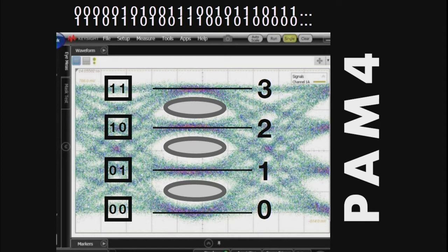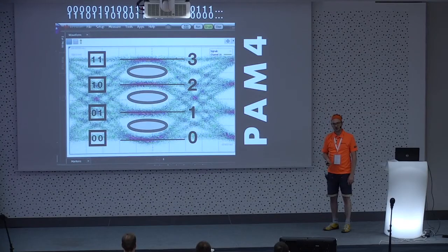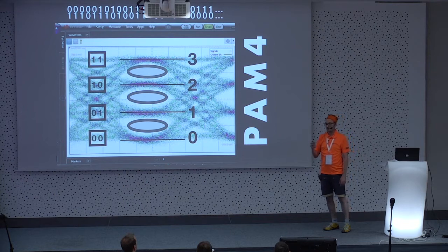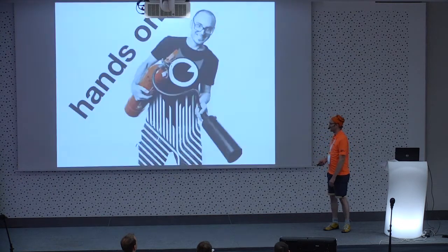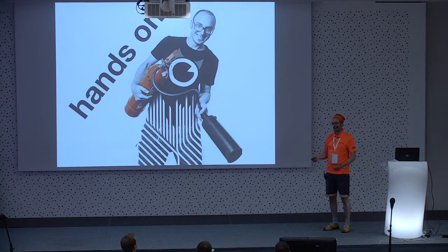The end of the theory part of my talk, which is now, is that acronym PAM4, which stands for 4-level pulse amplitude modulation. And the key point for the following slides is to keep in mind that on the same frequency we can do with PAM4, we can encode or modulate 2 bits instead of 1, and that's a really important thing to understand the ongoing thing now.